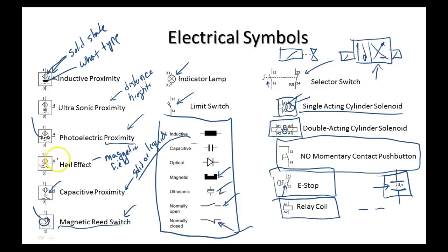But what you have the ability to do, even on your light sensors, just about all your light sensors are going to have a sensitivity adjust on there. So that means if you wanted to detect water but not detect glass, then odds are you could adjust it and make it do that. But if you set it at glass and water's dielectric was between there, then it would detect glass too. Does that make sense? So you can't really make it detect an object unless it's the only object that it'll see.